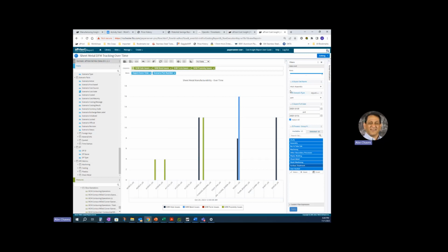But what I'm trying to show you by doing this is that this assembly is not all made up of sheet metal parts. You don't have to worry about that. The report will recognize that some of them are not sheet metal and only report on the sheet metal ones. If there were machine issues on this shaft here and I ran a machining report, I would get issues on that. Unfortunately, this doesn't have machining issues. It's a pretty clean design.